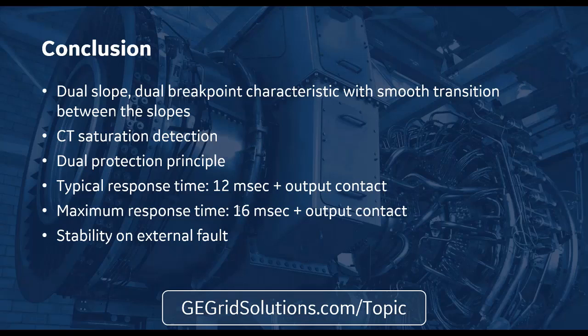The other application we've had on low impedance bus differential is on a retrofit application. A customer needed to reduce his arc flash incident energy, and it was existing equipment. We actually took all the existing CTs from, in this case, motor protection relays, and just put them in series right through the relays for the motor protection into a bus differential relay. And we were able to add bus differential protection to the system without having to go back and retrofit and add dedicated CTs.